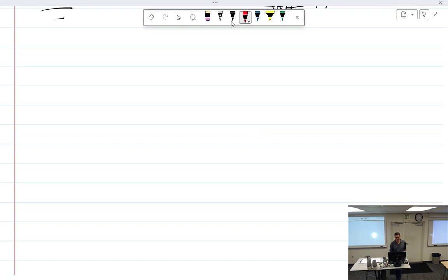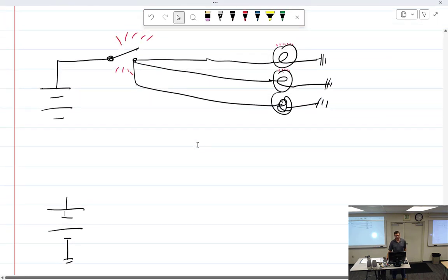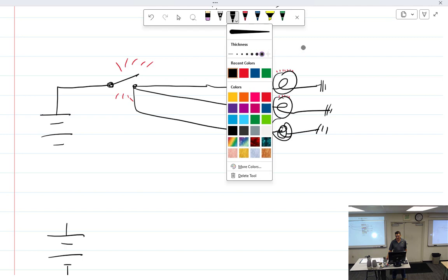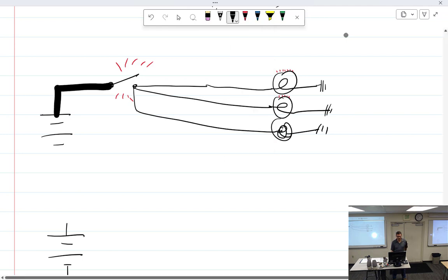What's that? I don't know. Okay, so let's look into that. So they said, well, if you're going to do this, then you have to run really big wire, because these lights use a lot of electricity. What affects the resistance of a wire? There's four things: temperature, diameter or cross section, length, and material. So I bought some bigger wire, but the same switch. And did that help me out at all?